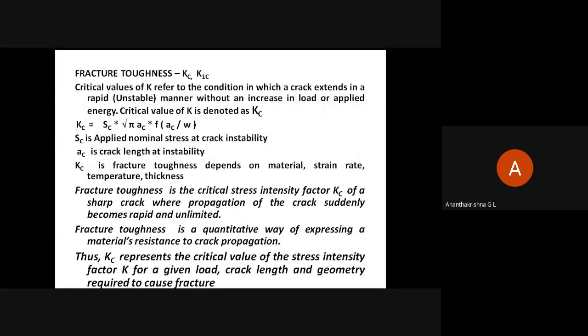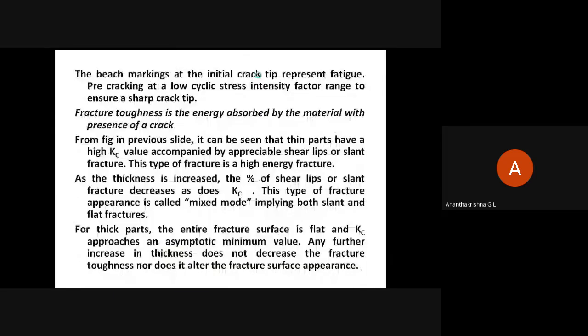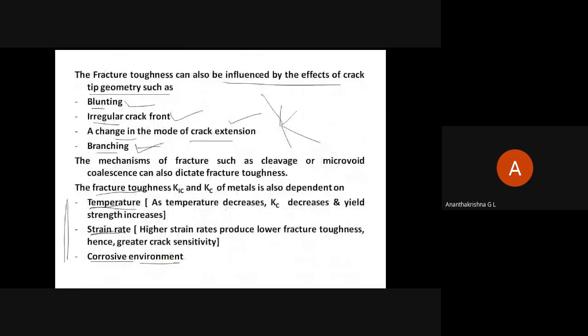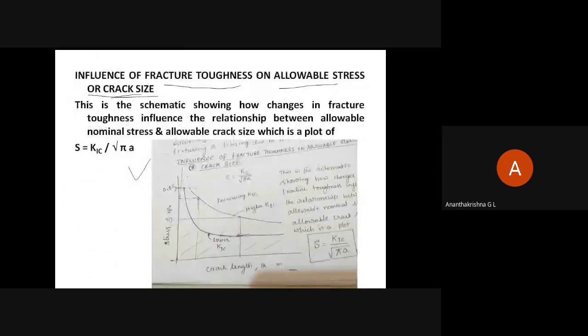So here we have the critical stress intensity factor KIC. The I represents the mode of fracture, that is mode 1. This I stands for mode 1, that is essentially mode 1 subjected to tensile loading. Okay, that's it. Please note down this sketch completely. This is lower KIC.